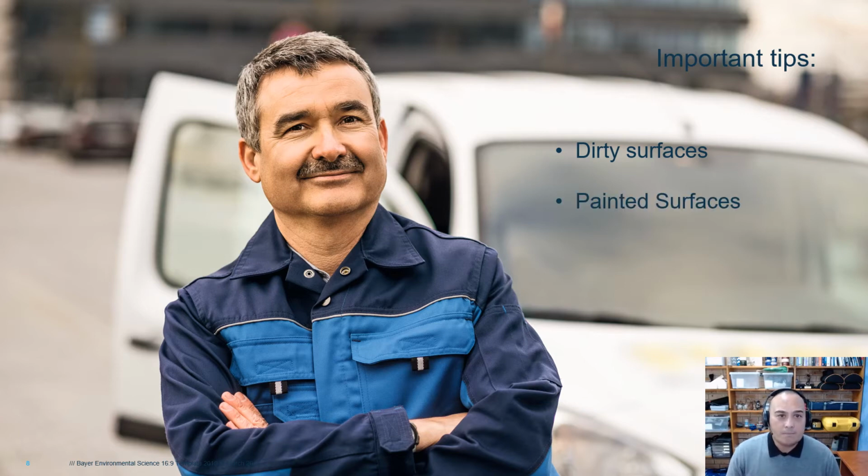Our second tech tip, runoff can result in streaks and marking of painted surfaces, particularly those recently applied that have not yet aged or fully cured. Pay particular attention with dark painted colours, and those that are facing the sun at the time of application. If a fence or a painted wall, especially if it's newly painted, has been in the sun all day, these situations are most likely at risk to show marking from over application, even just from plain water. So you need to be very careful, and we're going to have a look at even just what plain water can damage.